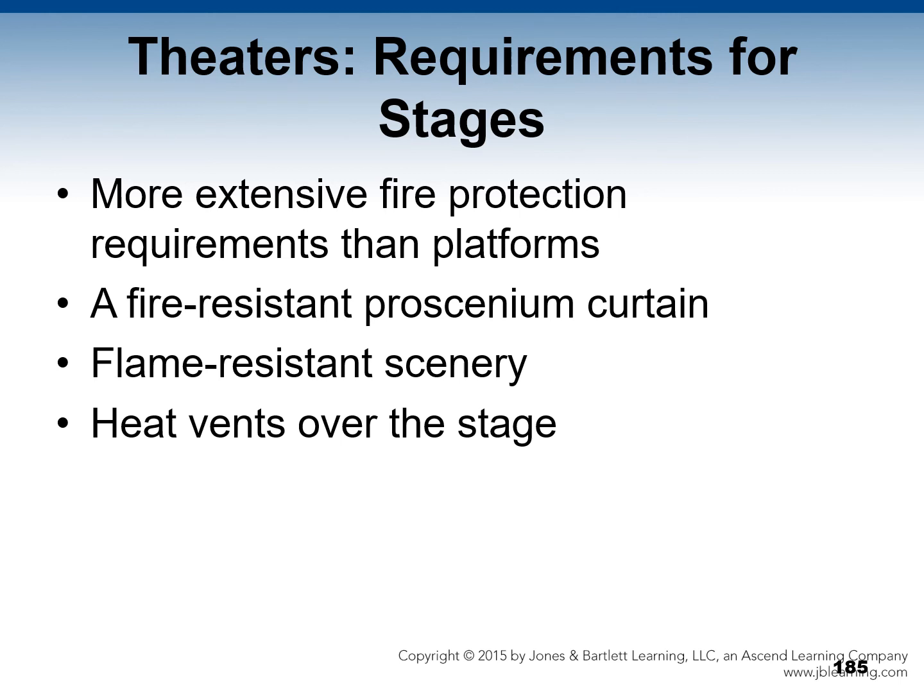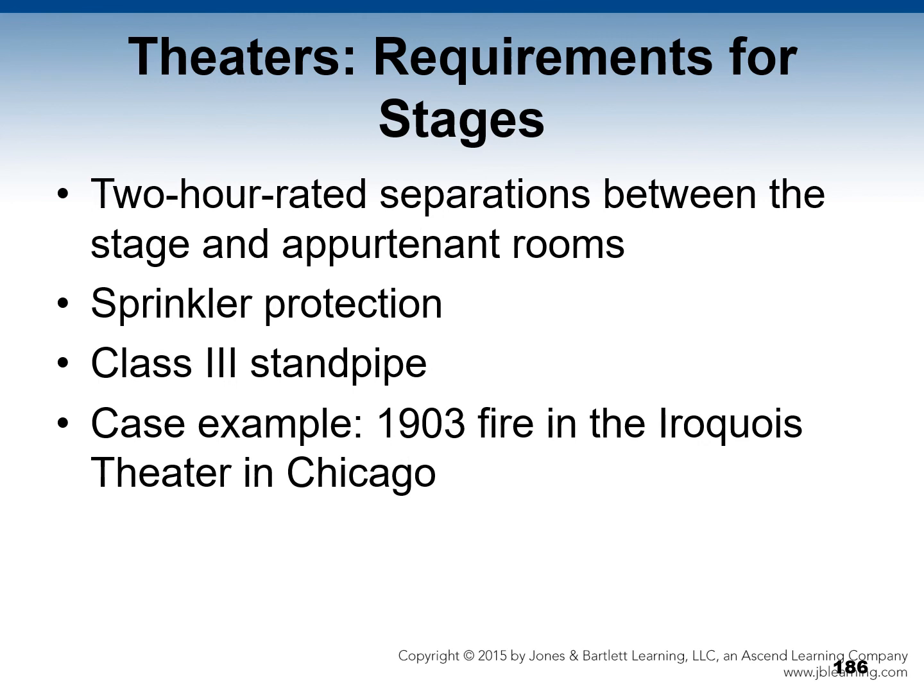There should be a fire-resistant proscenium curtain, flame-resistant scenery, and heat vents over the stage. Some more requirements for theater stages are that there must be 2-hour rated separations between the stage and appurtenant rooms, sprinkler protection, Class 3 standpipes with 1.5-inch hose and nozzle.